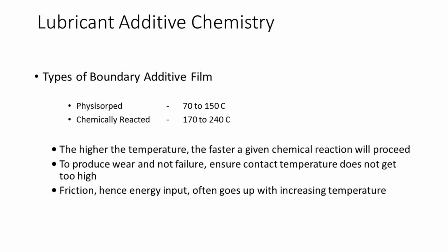Before considering how to model boundary lubricated contacts in a bench test, we need first to concentrate a bit on how lubricant additives work. There are two basic forms of additive protection available to surfaces that are either temporarily or permanently in intimate contact: physisorbed and chemically reacted. Changes in running conditions or test parameters, for example changing load or frequency of events, will usually cause a temporary change in the consistency of these protective layers or films, indicating some kind of limited dynamic stability.